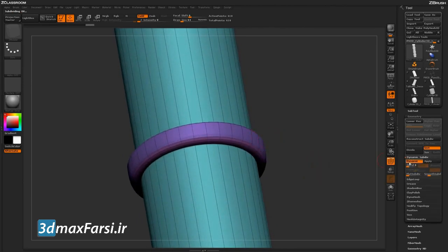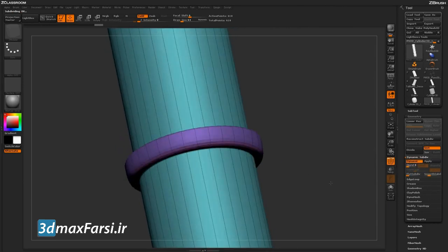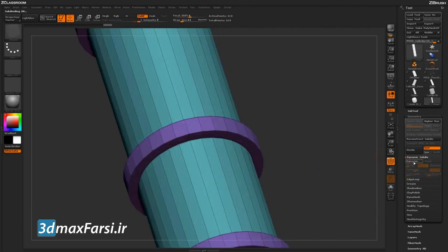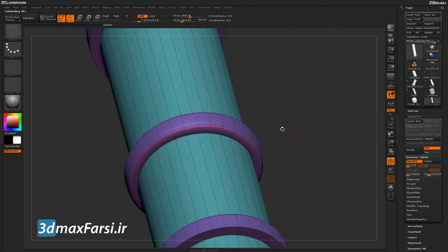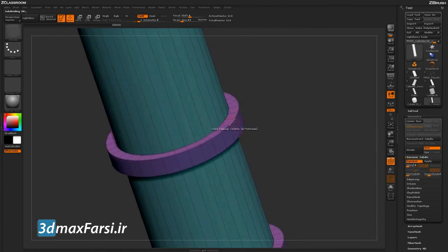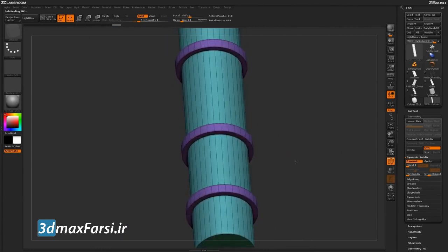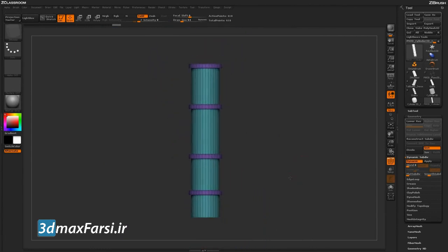Now, when you're using dynamic subdivision mode 2, you can toggle it on and off to see your original cage versus the actual dynamic subdivided one. There's a hotkey for this, and it's just Shift D and D. So you can hit Shift D to automatically turn off dynamic subdivision, or D to turn it back on. This is helpful if you're creasing areas on your model and you may not be able to select an edge precisely, so you can switch out of dynamic mode, apply that creasing to that area, and then turn dynamic mode back on.